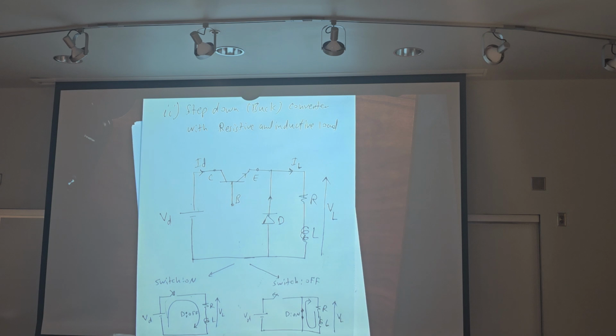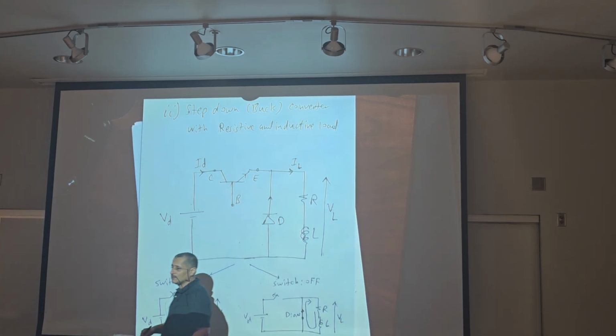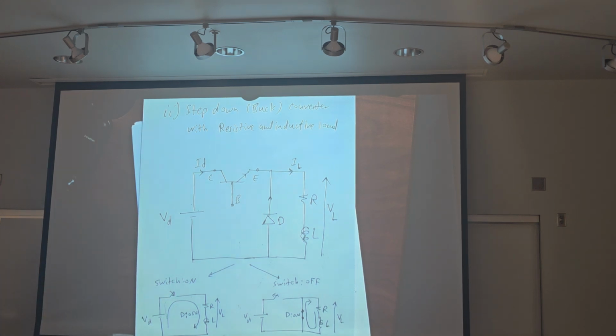This is the mode of operation for this diode. A Zener diode is different. A Zener diode should work in reverse bias and is used in stabilizer circuits, so no need to add a Zener here.